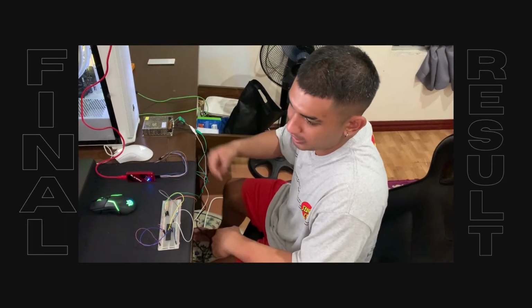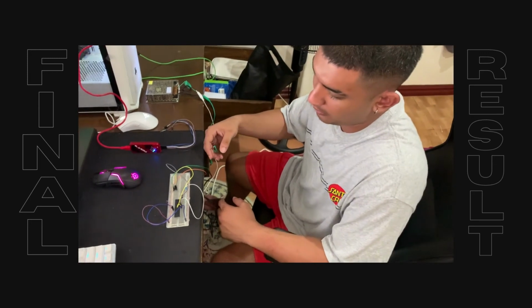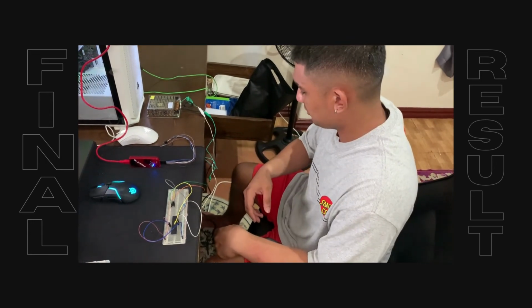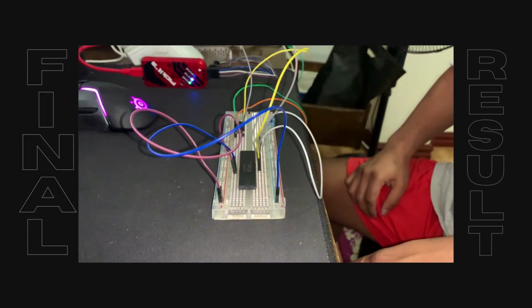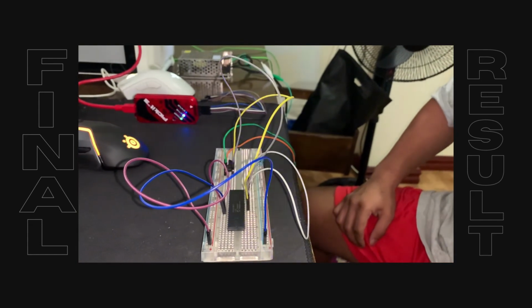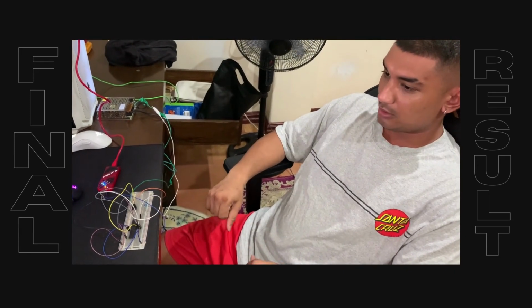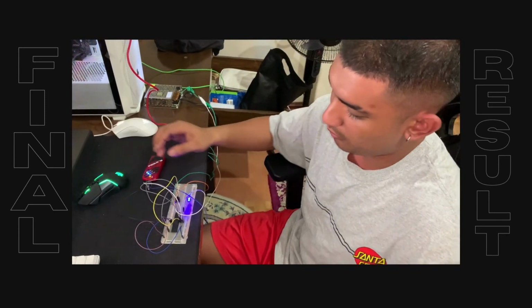So this is experiment 3 using Timer0, delay using polling and interrupt. In the first part of it, we have obtained that the LED light will blink for 250 milliseconds. Right now we have modified the Timer0 and made it a 2 second interval, and now we have achieved in this experiment the 2 second interval.